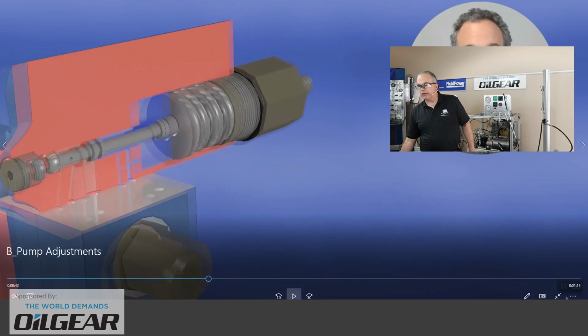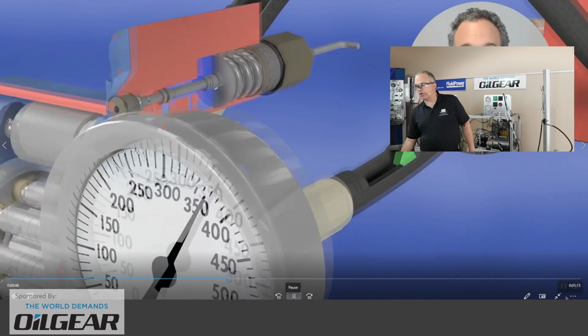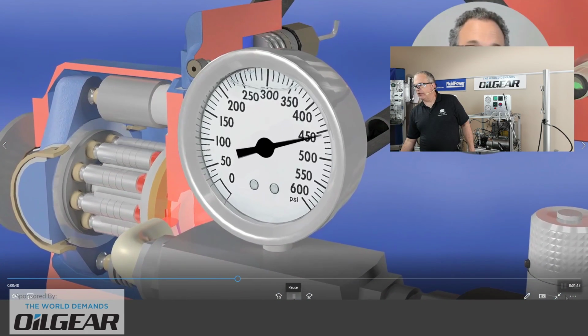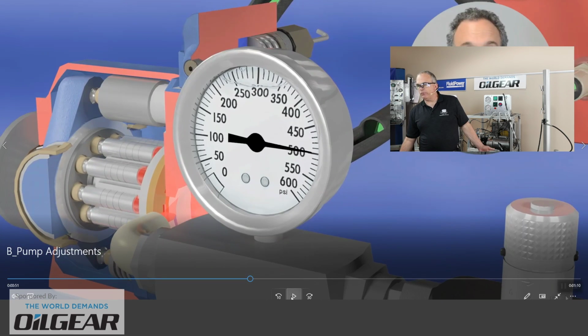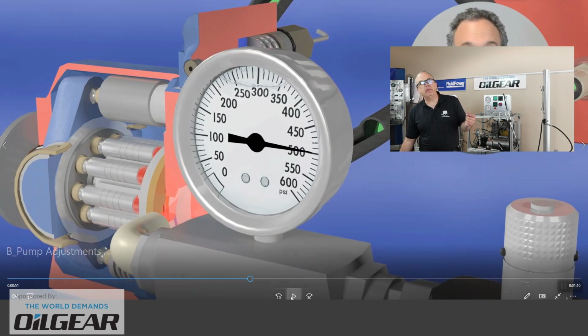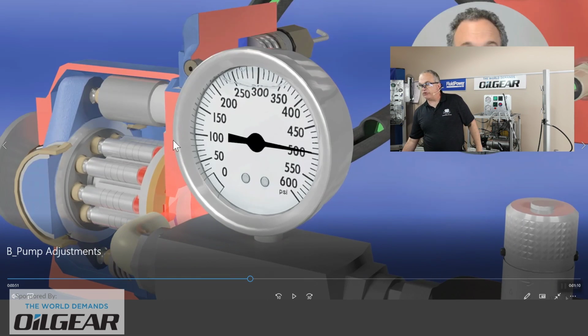What it is doing is working. Here we go. Let's increase our pressure here. Let's talk about that a little bit. So if we dial that Allen key clockwise, we come up to a higher pressure, and what can we say has happened? Well, it's just made it a little bit more difficult for that pump outlet pressure to shift that spool against that stiffer spring, and now our outlet pressure on the pump will come to even a higher level before the control piston that you see here, the large control piston, de-strokes the pump towards zero.